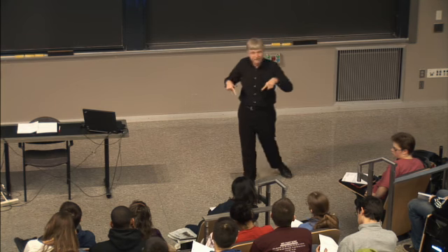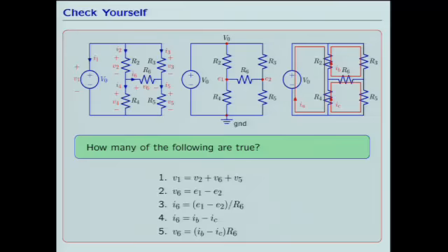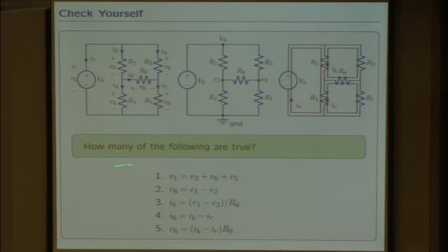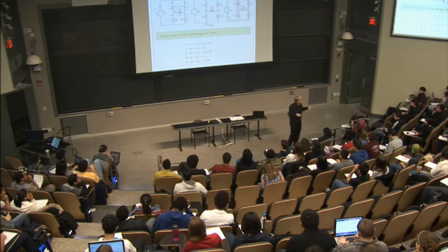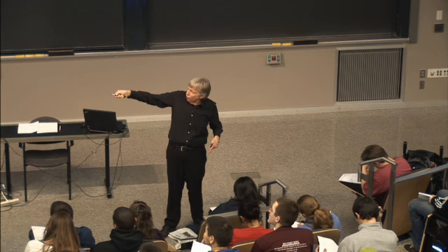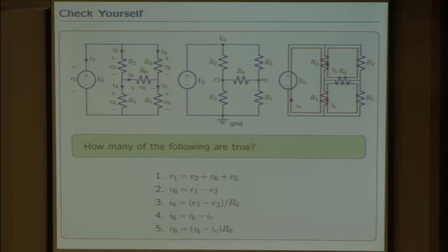Ohm's law is a little bit uglier when you use node equations than when you use primitive variables. When you use primitive variables, the same relationship would have simply said that V6 is R6 times I6. Because I'm using node voltages instead, the voltage across resistor 6 shows up as a difference.